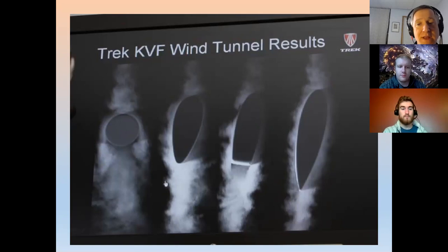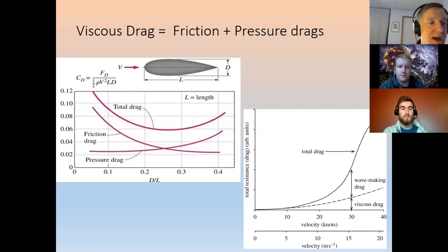And with modern manufacturing, like injection molding specifically, you no longer need simple shapes. You can deal with complex shapes. This is a really helpful diagram. You can spend some time with this and dissect this. The right one down here is looking at ship drag. So it's got a big wave drag component where you're lifting water up. The right diagram is looking at pressure and friction drag and total drag and optimizing that. It's got the coefficient of drag equation in it with the V squared term.